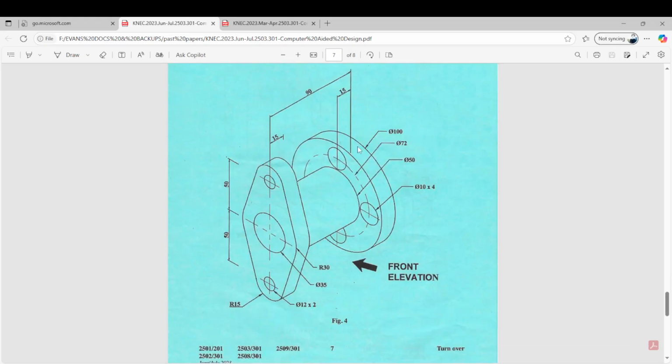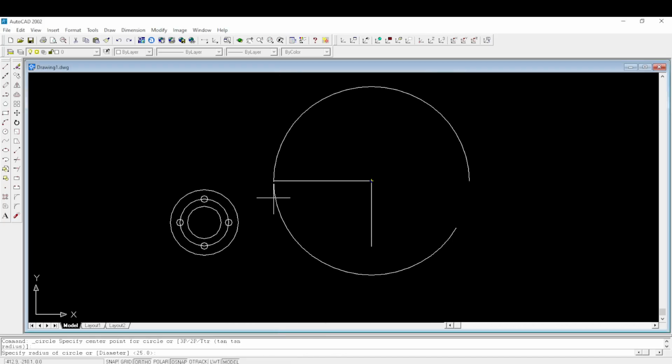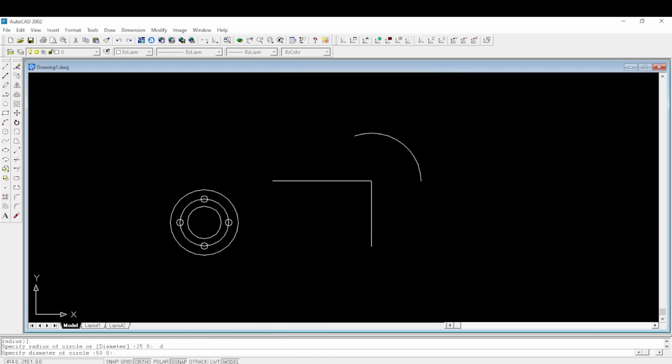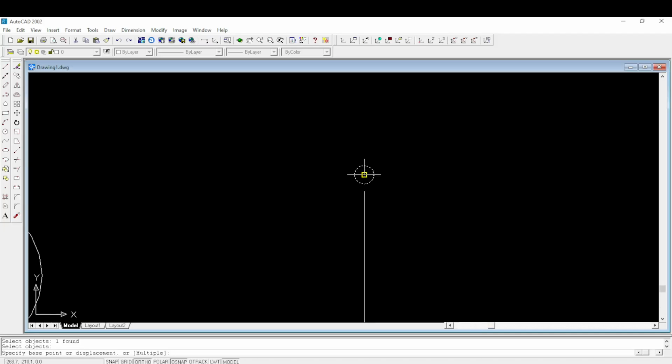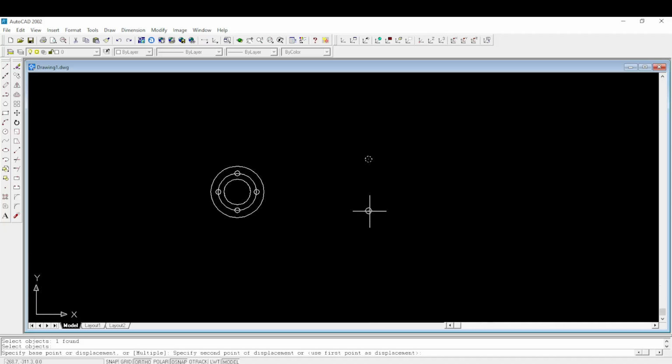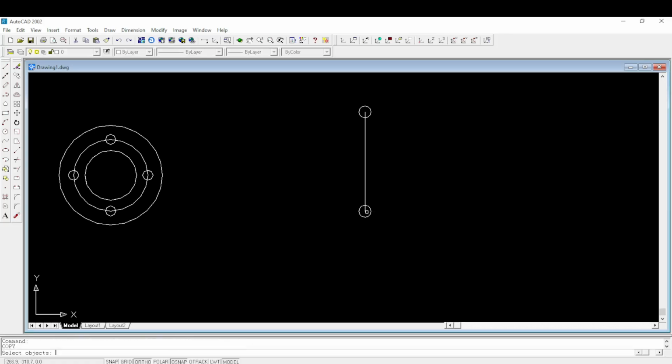we'll draw a circle of diameter 12, and also this one is of diameter 12 because we have been told it's times 2, so meaning it's this one. So diameter is 12. So D, enter, 12, enter. To avoid repeating, you can copy. You can just move, copy this one from that section, you copy it downwards there, enter.